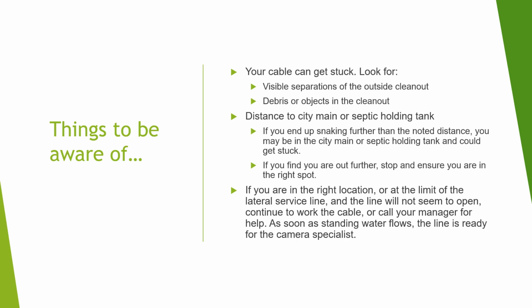Things to be aware of. Your cable can get stuck. Look for visible separations of the outside cleanout, debris or objects in the cleanout. Note the distance to the city main or septic holding tank. If you end up snaking further than the noted distance, you may be stuck in the city main or septic holding tank. If you find you're out further, stop and ensure you're in the right spot.